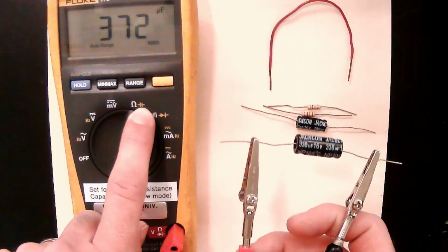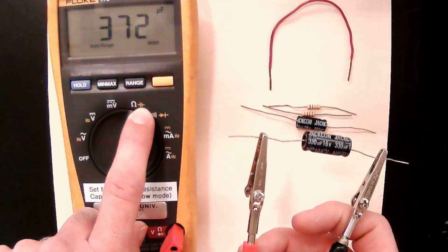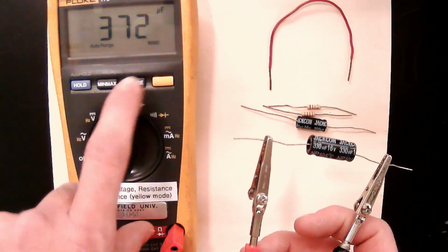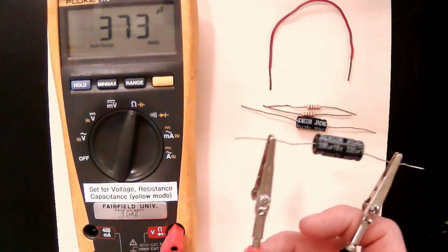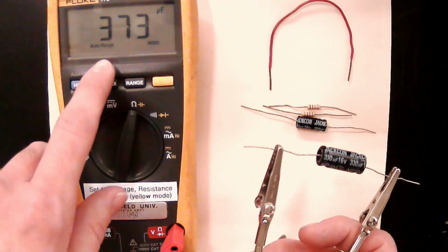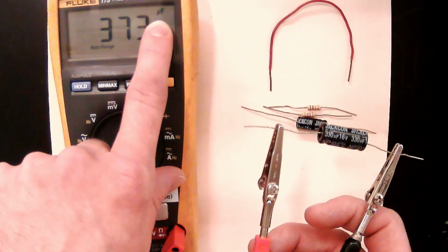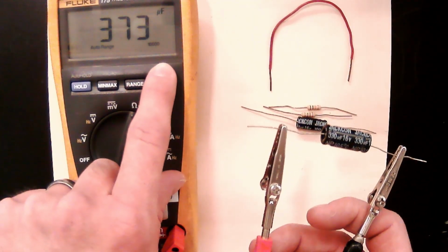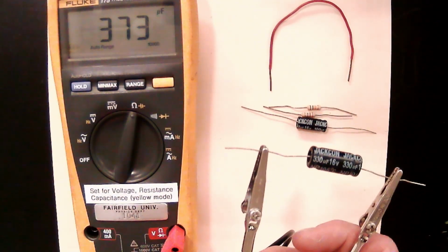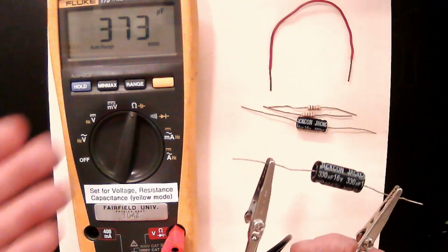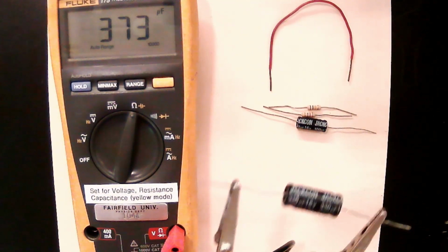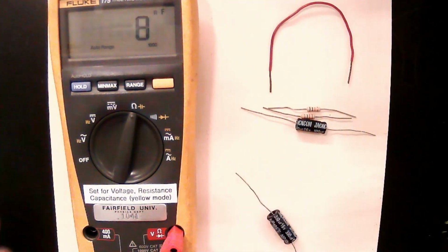This is noted up on the top right-hand side of the board, and you'll see the capacitance of this one that claims to be 330 microfarads is actually around 373 microfarads. Again, the unit is right up in the top right corner of the multimeter here. There are some manufacturing tolerances. It's close enough. This will be your actual value that you'll compare your data to later on.